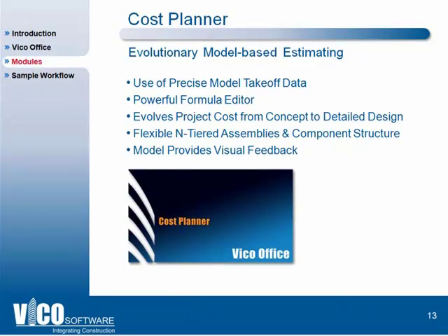Of course, the model that we have works with Cost Planner as well. Quantities are linked through Takeoff Manager, so each of the cost items knows to which element in the model they're connected. So selecting a Cost Planner item will result in highlighting that element in the model.